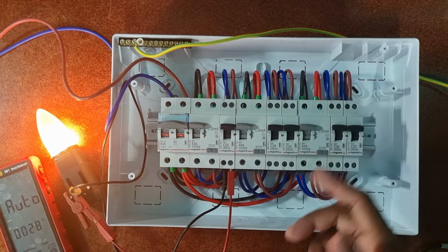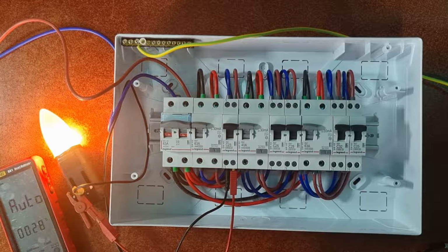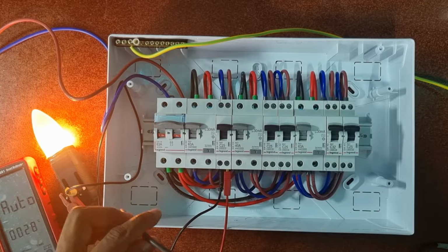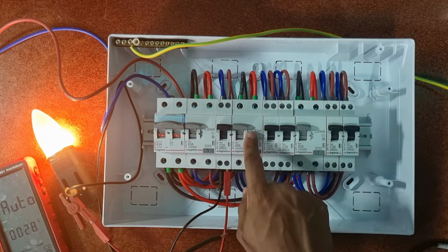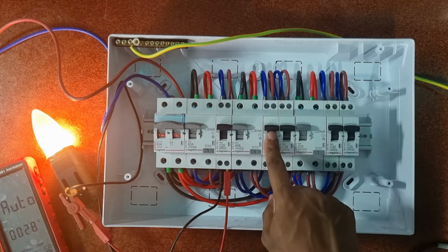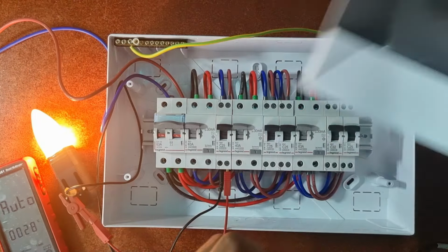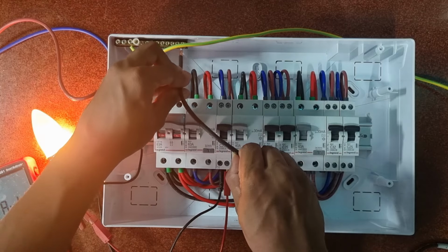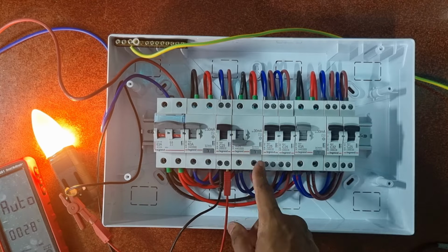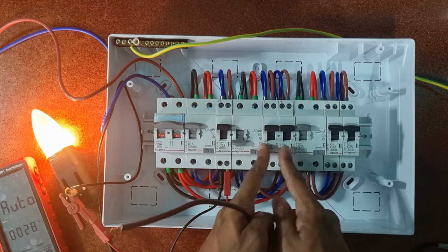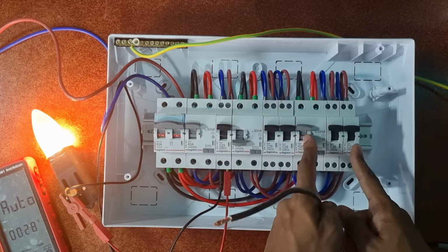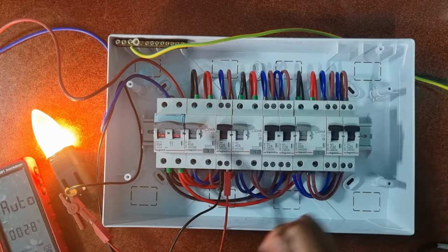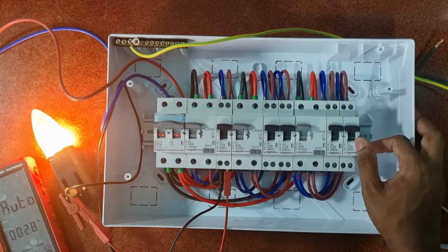Only one part of the house is switched off if there is a leakage. Even for this one, let me try this one. Let's say this one was for room number 2. This is room number 1, this is room number 2. In room number 2, there's a failure to ground and it trips. See, these two breakers are controlled by this RCD, these two breakers by this RCD, and this one breaker by this RCD. And there you go. This is very simple and straightforward to understand.